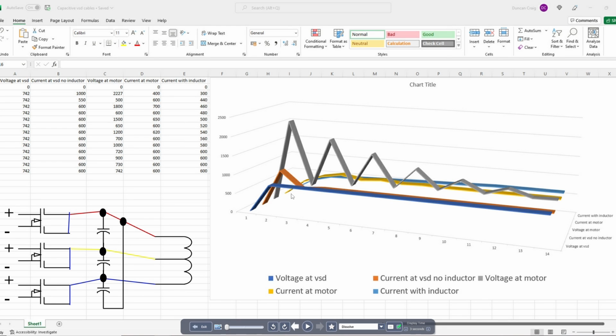This doesn't mean that you haven't got a problem before then, because this is a linear progression. So at half that distance you'd already have half of this problem. And depending on the type of cable, you could already have this at a much shorter distance. If it's a flat trailing cable, for instance, they are terribly capacitive.